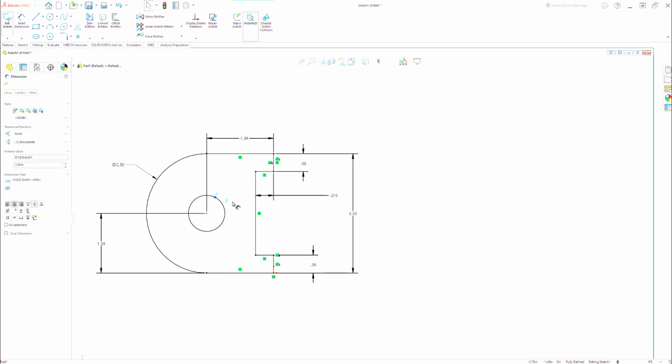We can do the same thing with the 0.76 and actually bring it out of the drawing shape. And you'll notice that I've placed all these dimensions on the outside of the shape, and that's a good general rule to follow. I'll clean this up, and we'll bring this a little bit closer so it's not way out in space. And the same with the 0.38. We're going to bring these in a little bit and kind of align them up.